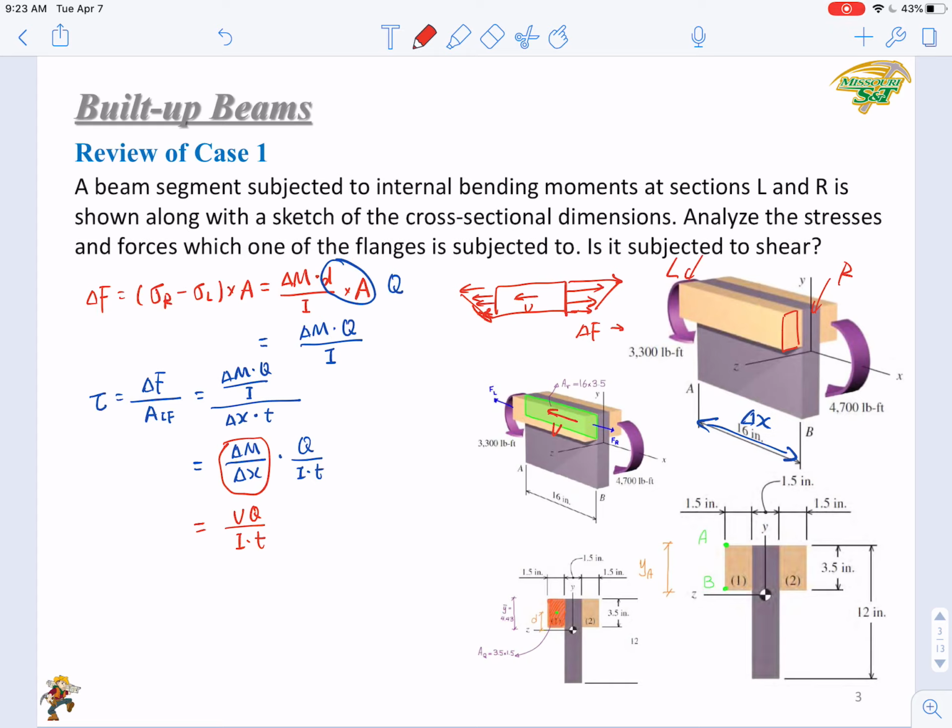In this case, we assumed that the flange is glued perfectly to the web, or the flange and the web belong to an integrated piece of material. However, in practice, the flange and web may not be bonded perfectly, but connected by bolts and fasteners.